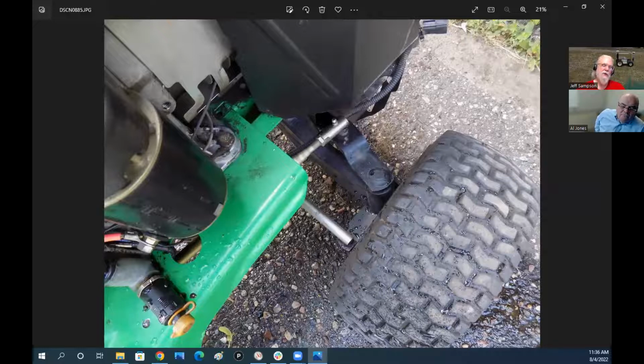As you turn the steering wheel, the arm moves back and forth like this. It pushes and pulls on this rod. And on my front end, it's got this lever sticking out the side, so that turns this side of it based on the steering wheel. And then it's got a second arm coming out the bottom of the steering down here. So this rod connects the one on the left side to give you your Ackerman angle to make that work. So anyway, that's where that's at.